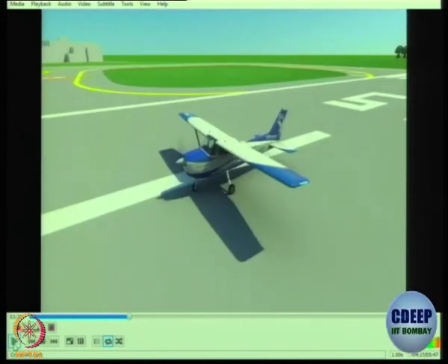I have a question. So why do you need a right rudder when you are not having any crosswinds? If you notice, he said that in normal takeoff, you will require a slight right rudder. And now if there is a crosswind from the left hand side, you have to put more right rudder. If there is a crosswind from the right hand side, you have to put less right rudder. Okay, let me show it to you once again. Listen carefully.